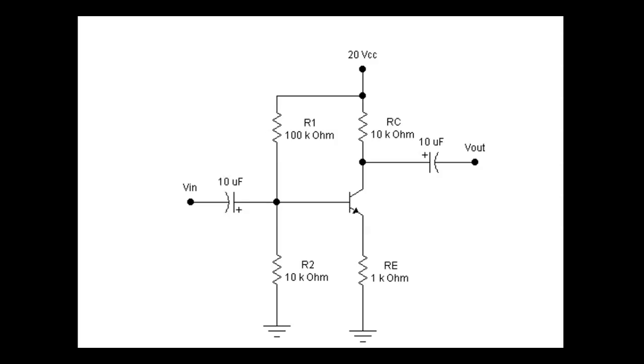To calculate current, you gotta know two things. You gotta know V, and you gotta know R. What sets the voltage across RE? VB. And that's why I wanted you to answer your own question, right? Understand? Because where does that voltage come from? It comes from the base.